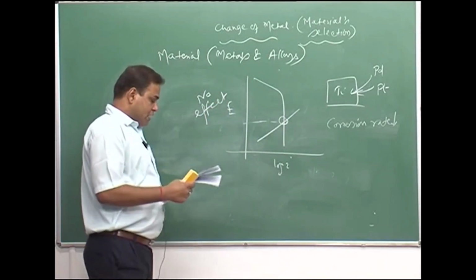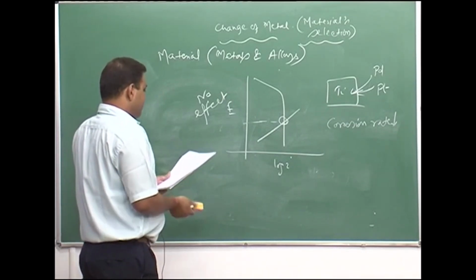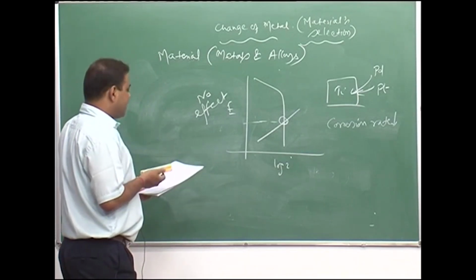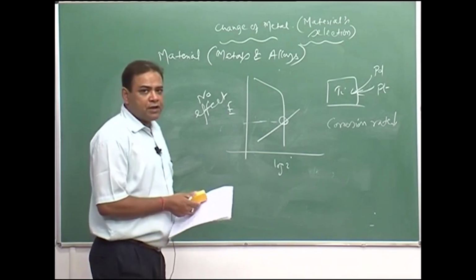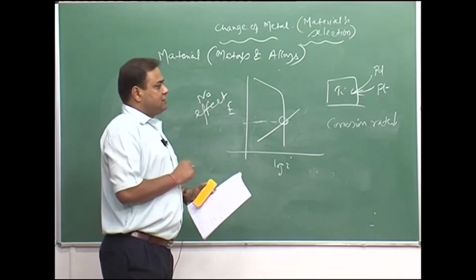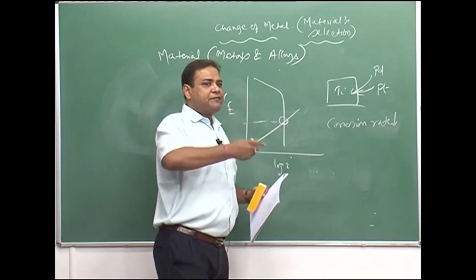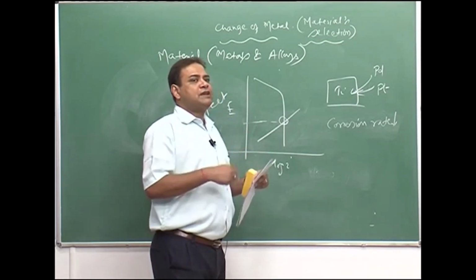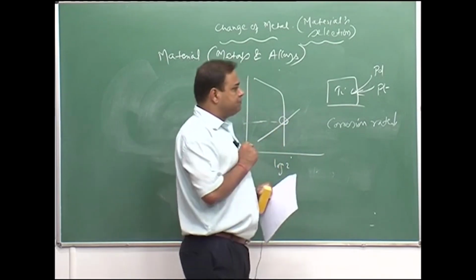Then we can also have a few more examples. We can have corrosion protection by alloying. Sometimes we add molybdenum in stainless steel in addition to chromium and nickel, that molybdenum improves the surface film adherence to the material, as well as it makes the film very impervious and stable.